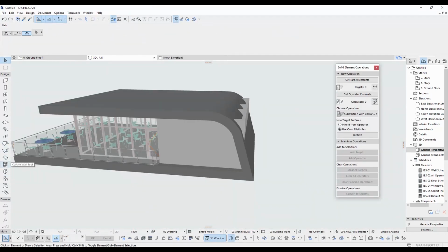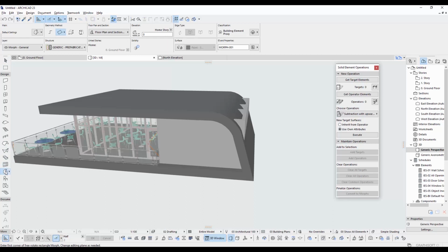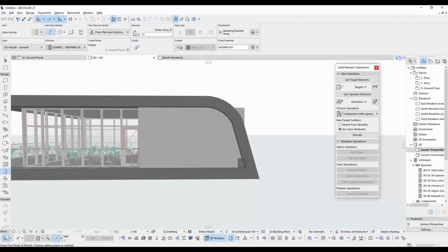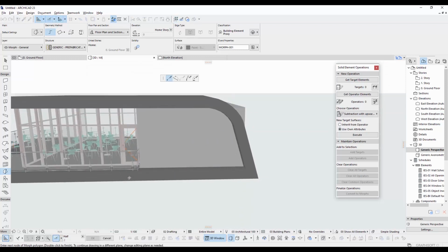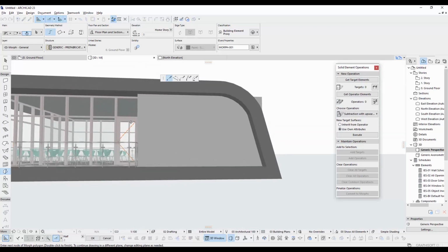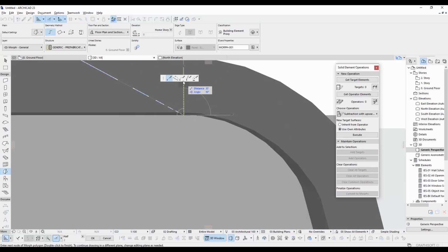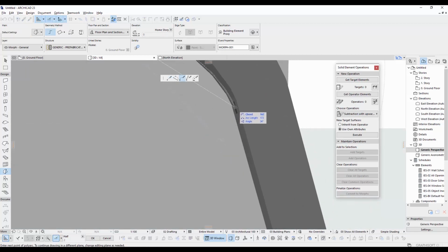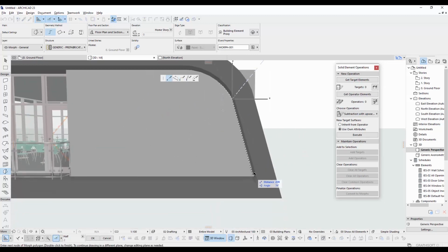Now I need to delete the excess of the wall. There are different ways to do it, but I'm going to show you the solution that you can use in every design. We are just going to determine a custom shape morph and give it an invisible layer and then intersect it with the wall. You can design lots of crazy things with that. Just draw a shape and intersect with your slabs, walls, etc. Of course, you can use Subtract too. That will open interesting shaped spaces onto your walls.